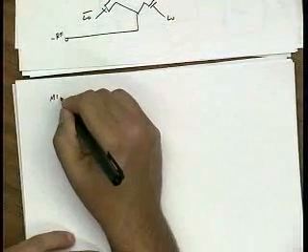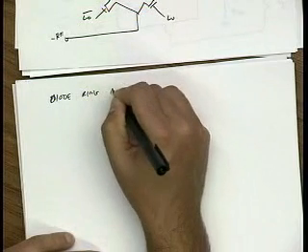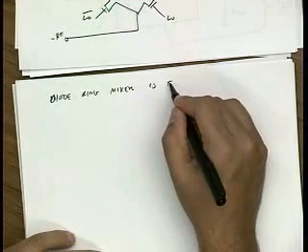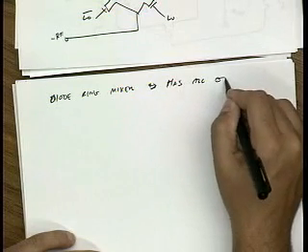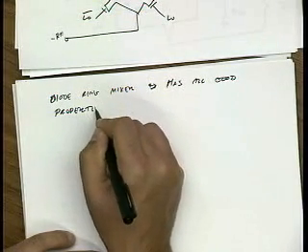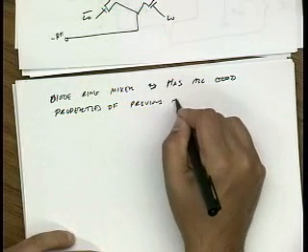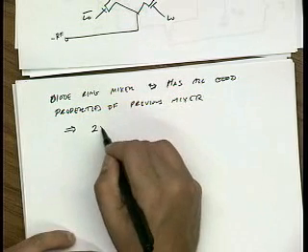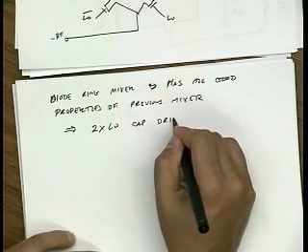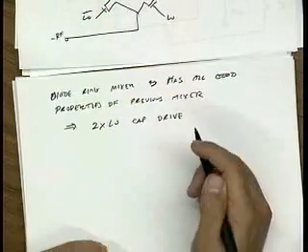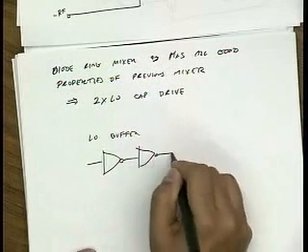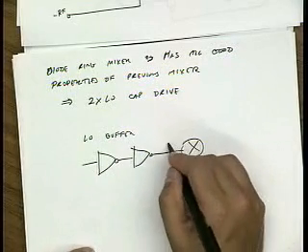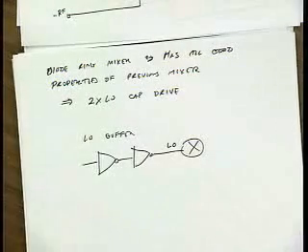So what can we say about this? So this mixer is fully balanced. It has, let's say, all the good properties of the previous mixer. It requires 2 times the capacitance. So if you're driving this, usually you're going to have an LO buffer, let's say it's an inverter chain. Because you have twice as many devices, you have twice as much capacitance.